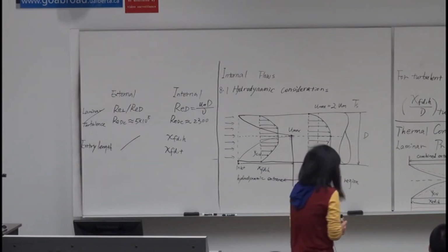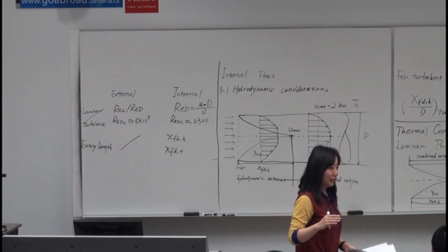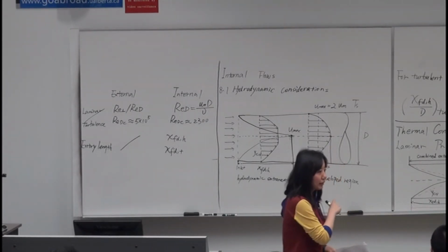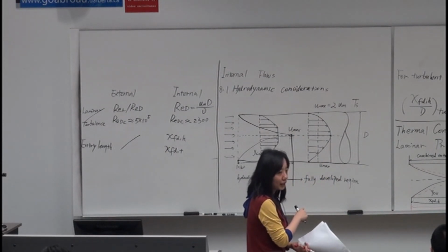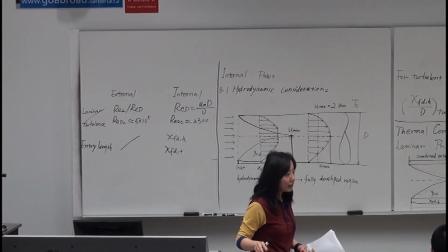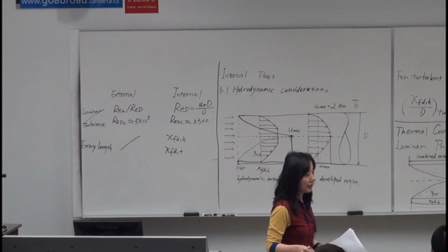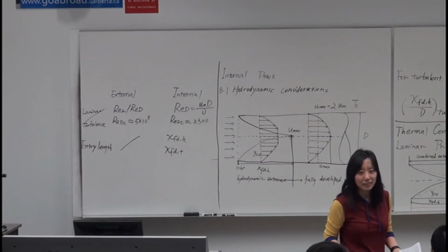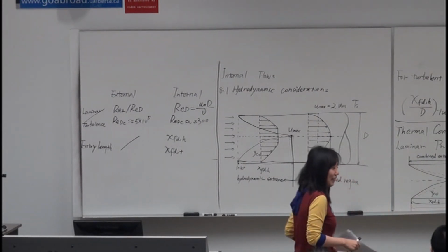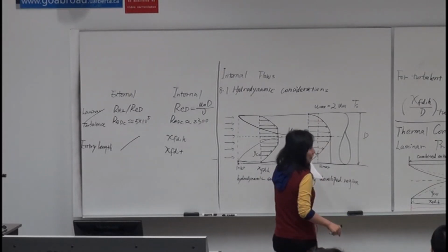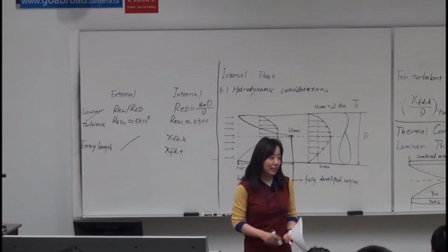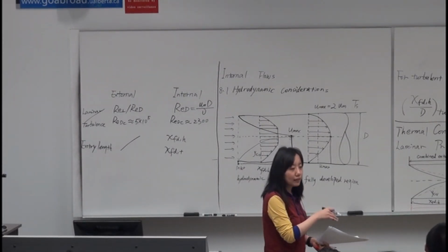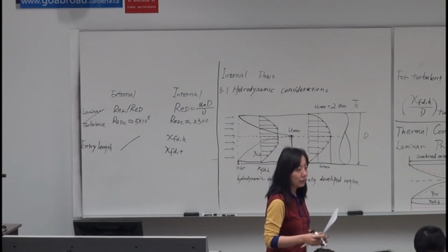No. The tube is hot, right? And the fluid gets heated. If the tube is maintained at that hotter temperature, at the very end, everything should be at the same temperature, right? The temperature profile changes even after reaching the fully developed region. What happens there? Why should that not look the same as our velocity profile? We will learn that later next week by establishing our energy rate balance.